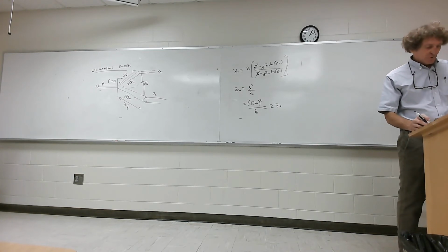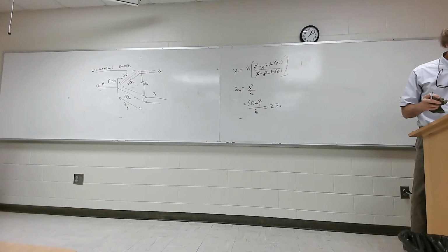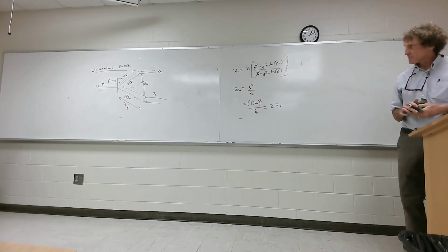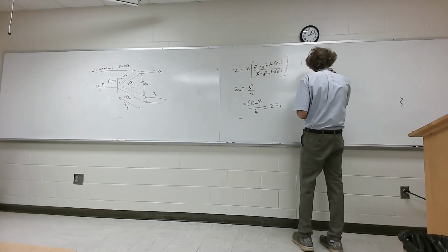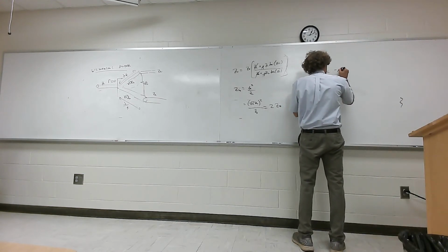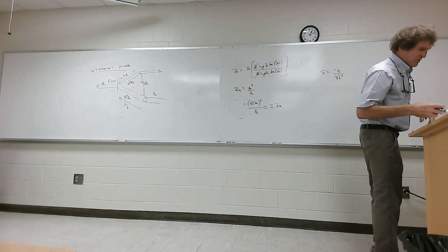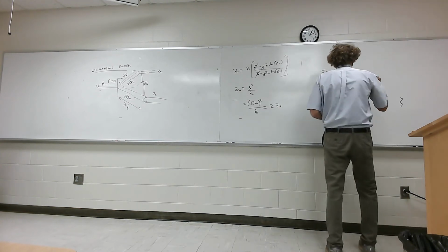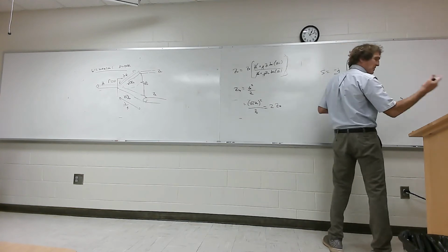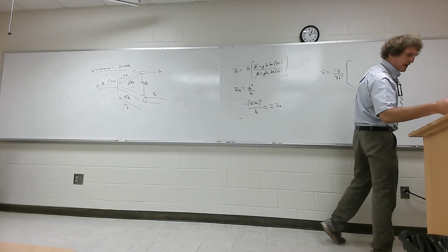So what are the S parameters? And he shows this on page 570. We could go through them, but I'm just going to show you this. The actual S parameters for a Wilkinson divider are minus j over the square root of 2. And it will not be over 2, but square root of 2. And then it's the same as the resistive divider.